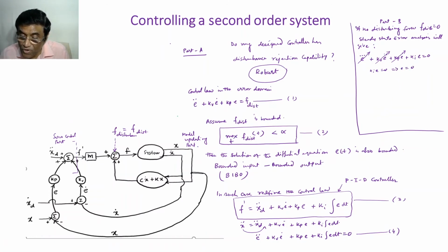But even if you do not have this term, the steady state error in a second order system was 0, right? So for PD control, when this is 0, that is, no disturbance force, the performance of a PID control and the PD control will be the same. So it will be a very bad idea to deploy PID control if you do not expect external disturbance in the system, because the more degrees of freedom and control gain parameters you have, the more costly the controller will be.